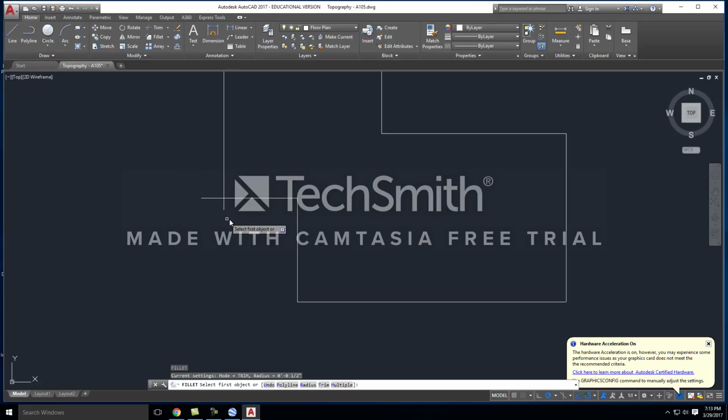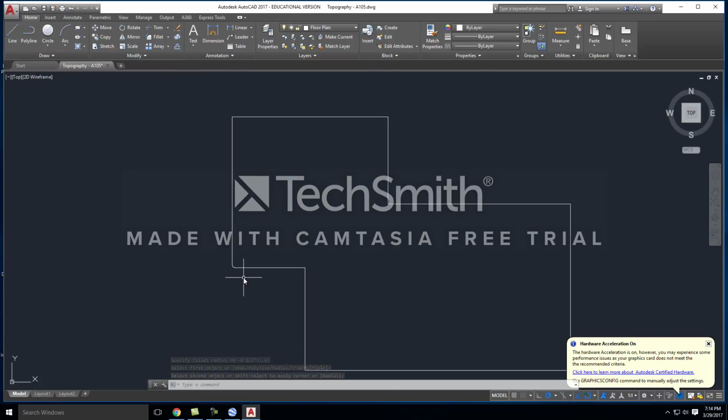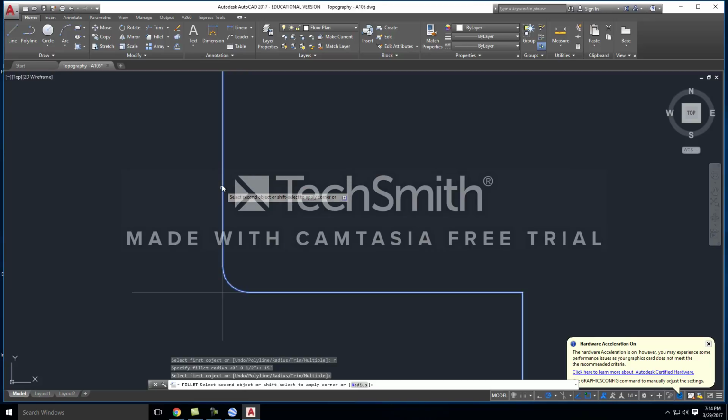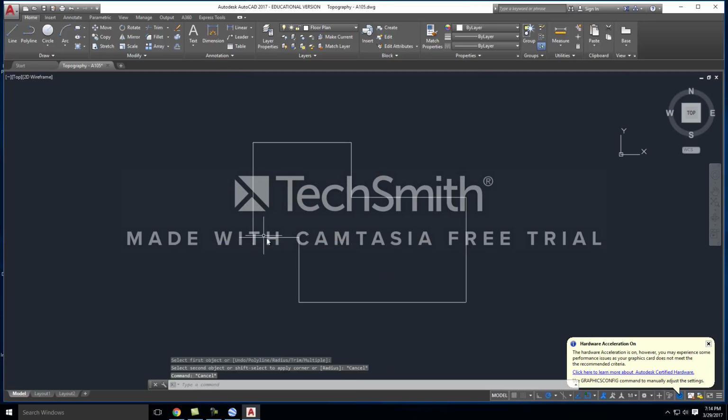So I do fillet, R for radius. I'll make this something much more noticeable, like 6 feet. I'll select my first line, and I will select my second line. So still barely noticeable, all right? But that gives you an idea of what that does. Fillet, radius, let's do like 15 feet. You've got to get something that's more noticeable. Wow, it's still hardly anything. But you guys get the point, okay? So that's what the fillet command does.